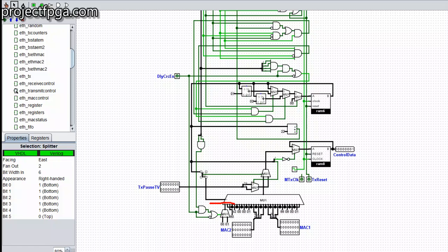What actually happens here is this multiplexer, this is another multiplexer here. So this says at the initial beginning of the byte count, when the byte count is 0, because bit 0 of the byte counter went into here, the input at this 0 is supposed to clock out. So it's now telling it, if delay CLC is not enabled, then it should turn this multiplexer on, and if this multiplexer is on, the first byte to be sent is 000.